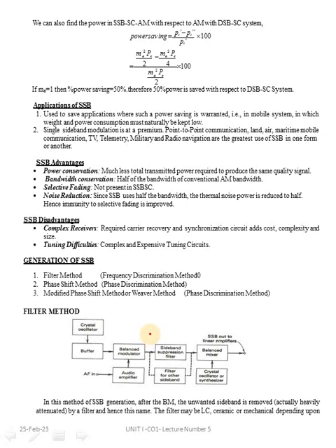From the name itself, it is frequency discrimination. The unwanted frequencies, the upper sideband or lower sideband, are eliminated using selection filters. Either we can eliminate the unwanted frequencies by using the filter, or we can choose the desired frequencies with the help of this suppressing filter. This is the block diagram: crystal oscillator, buffer, balanced modulator, and here we give our input signal, AF input, audio amplifier. This is called the frequency discrimination filter, and here is the outcome, the balanced modulator output.